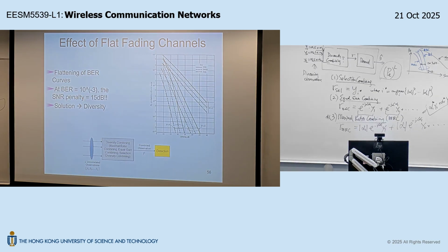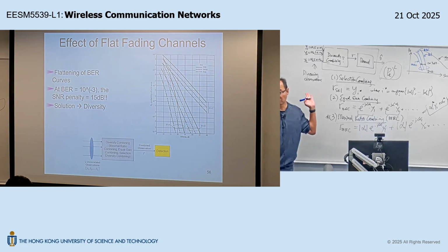So you need ADC for the first path and ADC for the second path, so that you have the digital baseband signals from the two receive antenna data path. Is that okay? Then, after you have this, you have the baseband processing. For example, the diversity combining can be implemented in the baseband, right? So that would be a naive way to implement two-order receive spatial diversity.